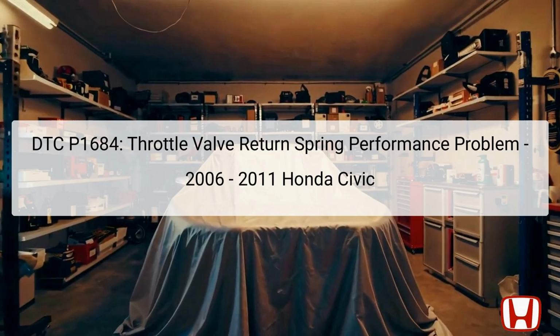The throttle valve, which regulates the amount of air entering the engine, is highlighted as the component of interest here. Its return spring is crucial for ensuring the valve returns to its closed position when the accelerator pedal is released. If this spring malfunctions, it can lead to unintended acceleration or poor engine response. Therefore, understanding this DTC is essential for diagnosing throttle-related issues that may arise in the Honda Civic.